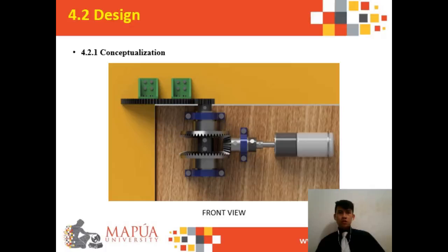The bevel gears are attached with a roller clutch bearing that locks on the driving shaft when driven on one side and rolls freely when driven in the opposite direction. The clutches are set in a way that the bevel gears will only transfer torque in one direction. The bevel gears then drive the bevel pinion, thus the generator shaft moves in only one rotation.